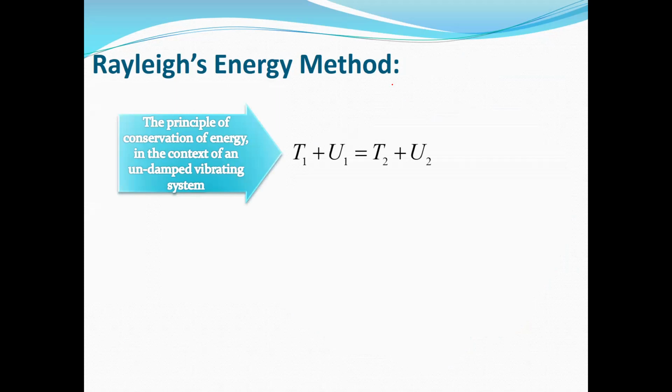I mean, we don't want to use this method in our exam. I just want to have a very short introduction to this method. Maybe in your assignment, you need to use this method to extract the lowest natural frequency in your system. So this is an approximation. The natural frequency obtained from this approximation method is usually less than the real natural frequency in your system.